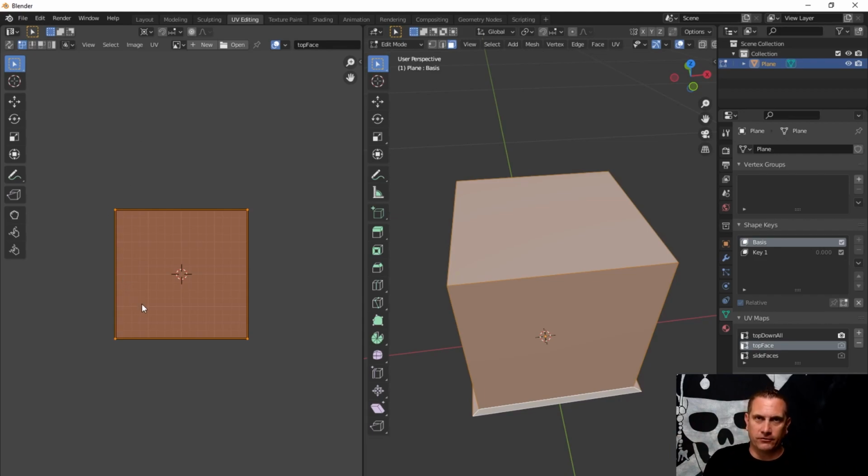Let me show you the difference just real quick. I'll move this over here. With the bounding box center, I'll hit scale and 0, and it'll end up in the center. Okay, but if I change it to 2D cursor and hit S0, it'll put everything into the center of this 2D cursor. Okay, not a huge deal. Basically, again, to go through that, Shift S, cursor to selected, and then make sure this pivot point is on 2D cursor up here. Grab everything, S0, and now it's in the very, very center.